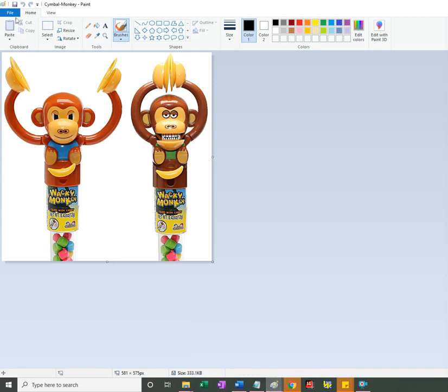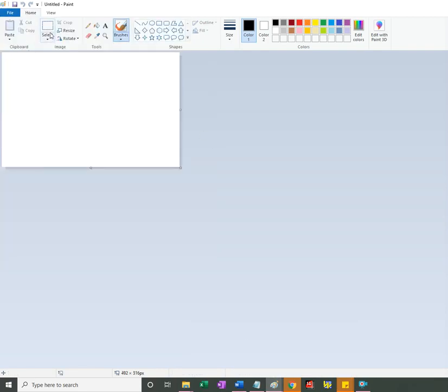So the dyad of the RRP type is rather going to be one where the piston or the slider and the pin joints are overlapped. There's no offset, and for good reason. With an offset, you induce a moment of the slider relative to its guide.